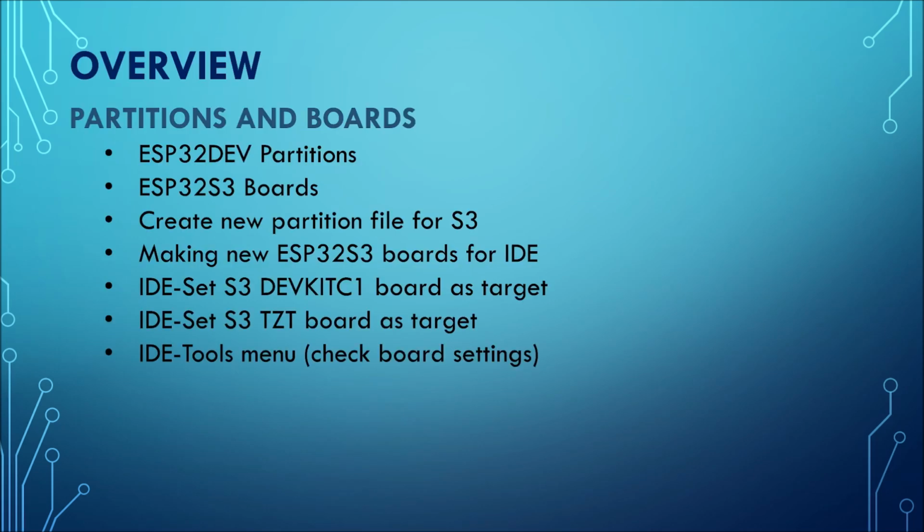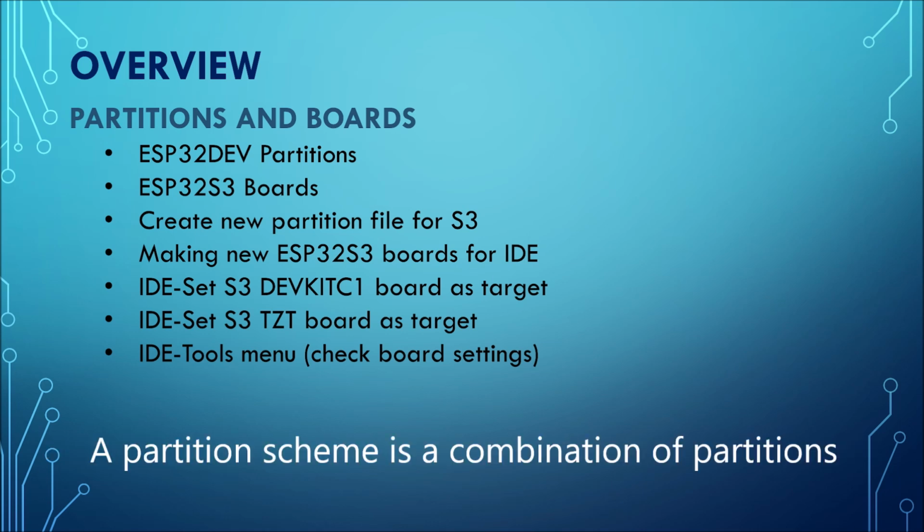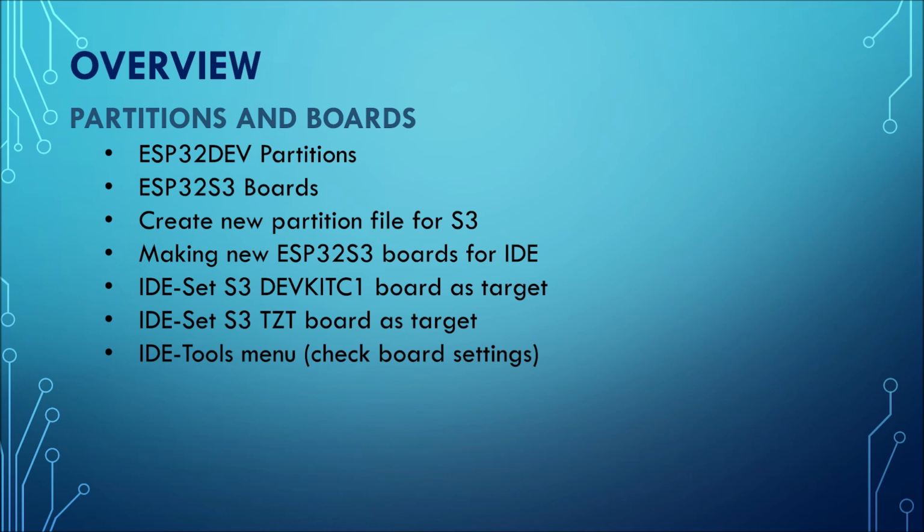where we'll talk about partitions and boards. We'll first have a look at the ESP32, then we'll go on and see what we can do with the ESP32 S3. That will lead us to creating a new file just to handle the S3 boards we've got, as well as being able to add into the IDE definitions for the new boards for this project.